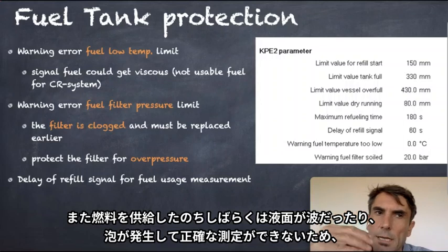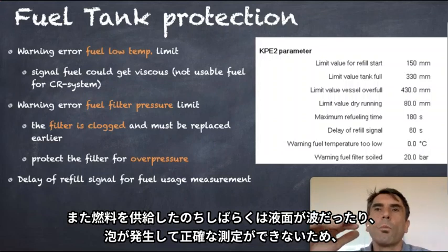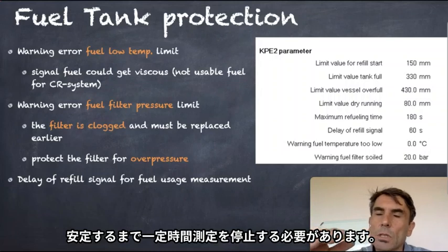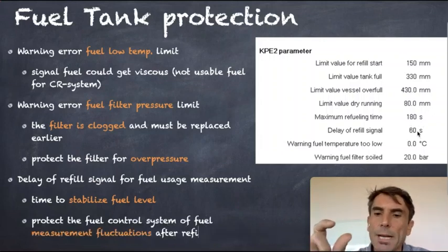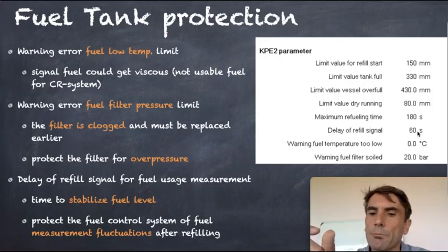And you have to understand, if we refill the tank, the fuel goes into the tank and they have like waves or small bubbles or something in the tank. So it needs a little bit of time to stabilize the fuel level in the tank, so that we have a stable level again before we start measuring the fuel consumption or the fuel usage in kilogram per hour again.